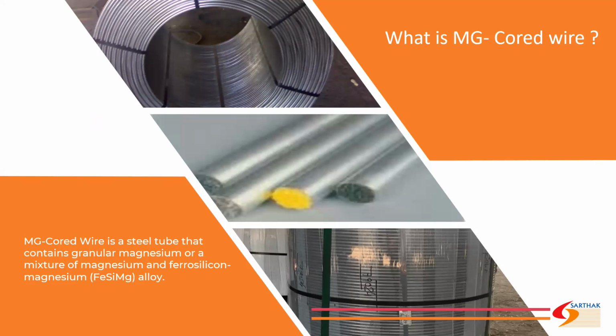Wire feeding machines also come with logic programs which help us add the exact required quantity of the wire into the melt. It also calculates the exact quantity of magnesium wire which we require. It depends on your melt weight, the sulfur of the base metal, and your desired magnesium. So by using an empirical formula, it automatically calculates the length of the wire to be fed into the molten metal. So core wire looks like this. It is a CRC sheet, and inside that we fill the mixture of magnesium and alloys.